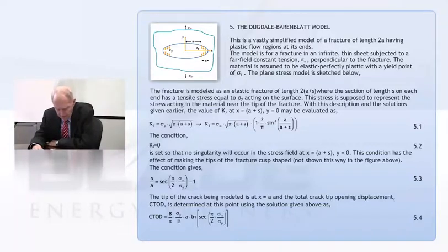When I have seen this, I've had the impression that, gee, if I would have done this, I would have used the ultimate strength. But as it turns out, in the codes, they use something in between. So it's sort of a compromise. Nevertheless, you've got two regions of constant stress applied at the tips of the crack, and they are holding the crack closed desperately because they're at the yield point.